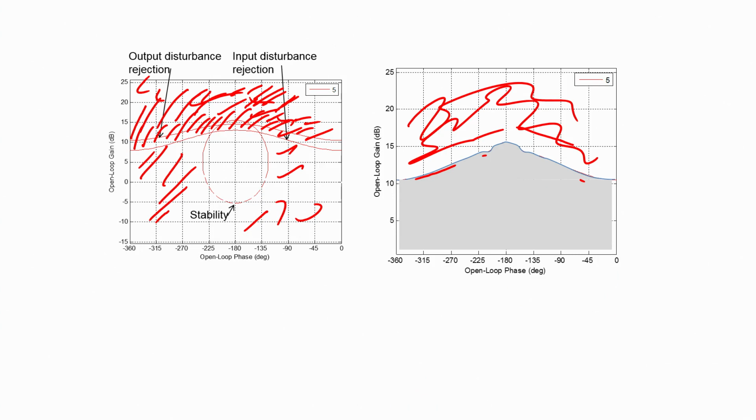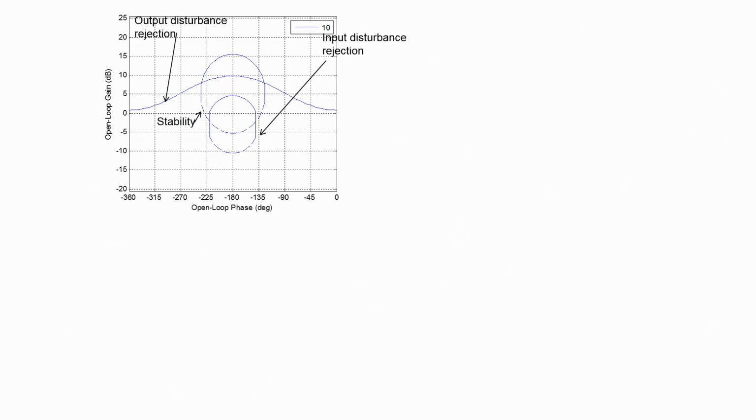Now we have undertaken computation of the bounds at one particular frequency, determination of its intersection at that frequency, and hence determination of the permissible area in the Nichols plot where the loop gain can lie at a particular frequency. We have to now repeat this at other frequencies of interest to us within the frequency range that the disturbances affect our system. So this has now been repeated at 10 radians per second, and the 3 bounds have